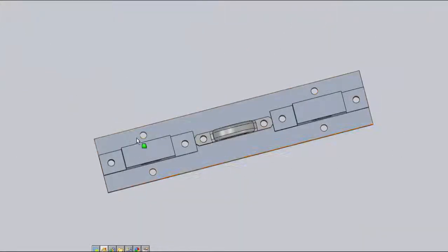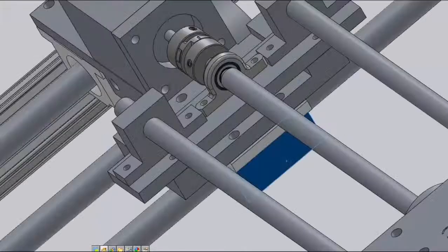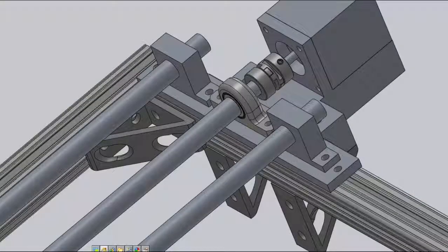This model is very similar, except it has these extra folds here for mounting on the large nut connector. While the aluminum stand is bolted to the large nut connector, the shaft holders are only bolted to the aluminum stand. This makes it easy to align the shaft holders so that the guide pins and the lead screw are perfectly parallel.